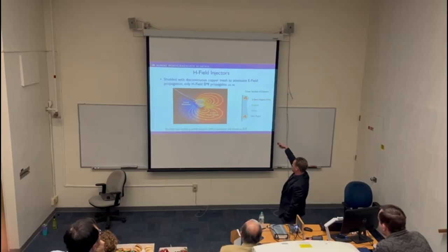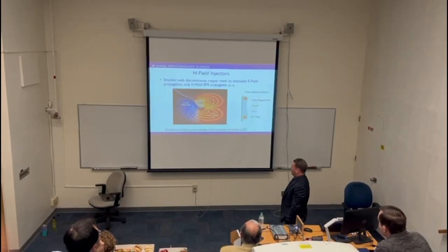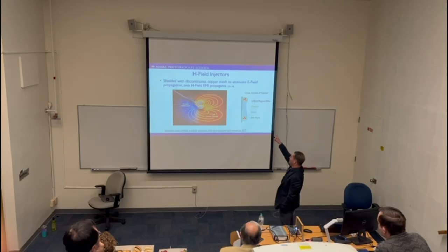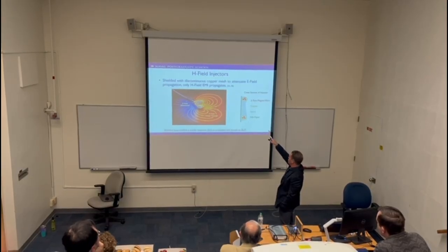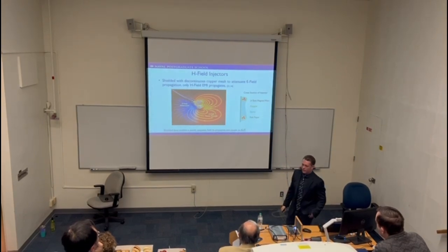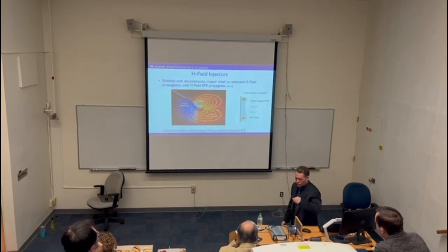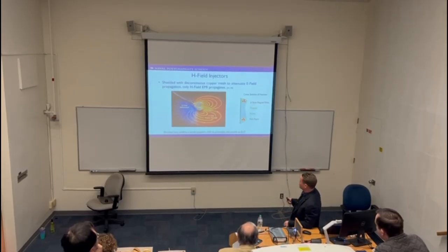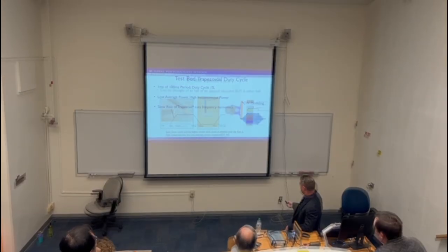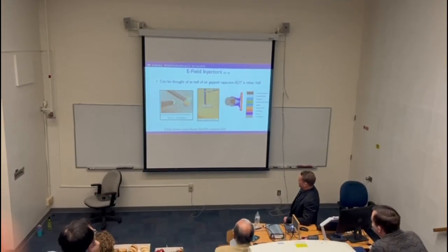This is just a little cross section of the injector that Richard and I have been working on this whole manufacturing process for a bit with the 3-turn magnet wire. You got the copper mesh that I use for the shielding. I got the epoxy and fish paper, basically all insulators, and create that hard structure where I can walk up on something and not worry about shorting it out to the device under test because it's all insulated.